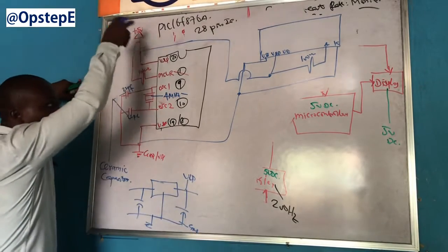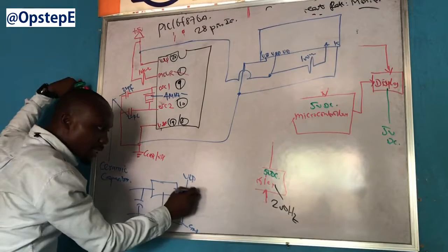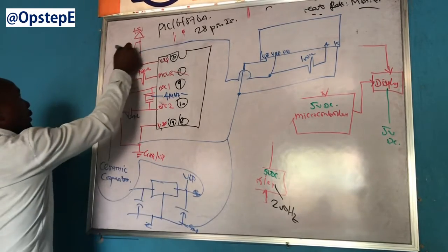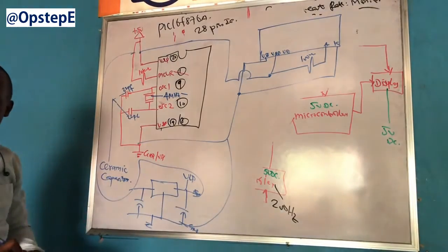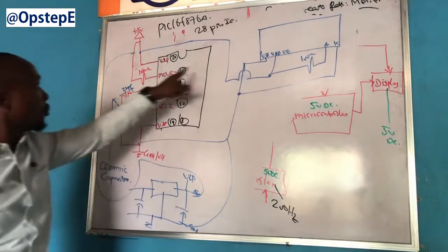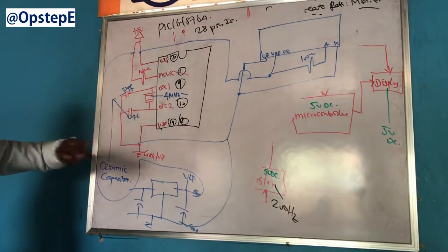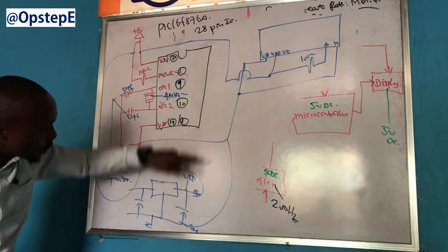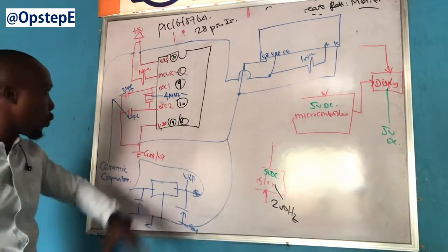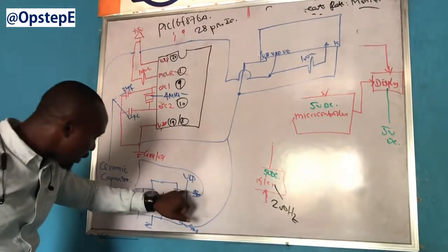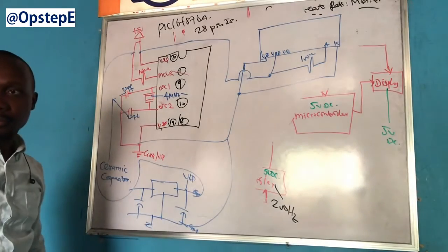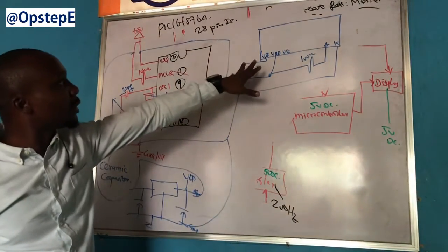So all those that are VDD are connected to this place. All those that are VSS are connected like this, while the VDD ones are connected something like this. Do you get the point? So that's why I started with the supply first, and then came here. So when I say VDD, all of them are coming to this point. The way the wire will then run is what differs. You go through different routes, but eventually we don't worry, and the same for the ground. So this is how you start.